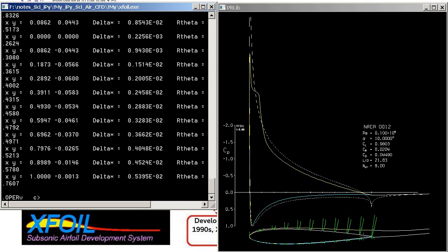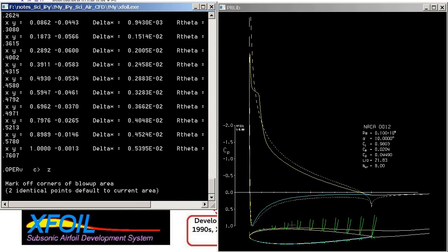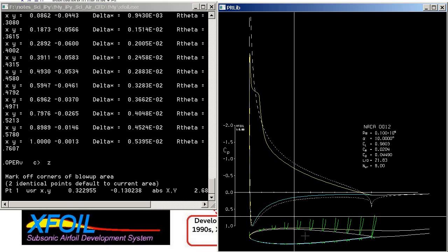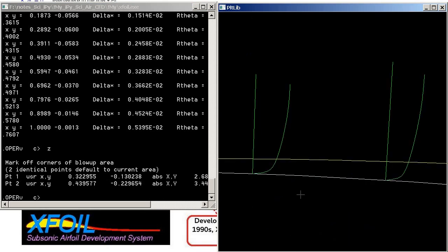So we can zoom in on particular airfoils at particular distributions by typing the Z command. And now you have to choose what you would like to increase. So now we can see the distribution of speed. The vertical line is actually the height, and the green line is the speed. At this height we have the speed which is approaching the speed of the free stream, and at this point it drops to zero close to the surface of the airfoil. The same is here. Okay.